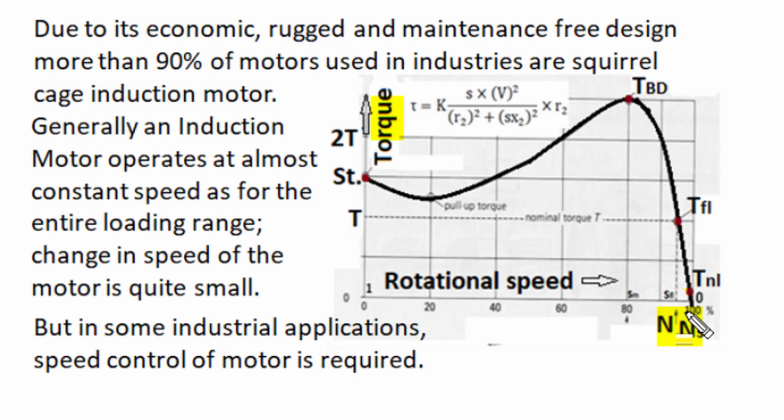At no load conditions, the rotor of induction motor rotates almost at the speed of the rotating magnetic field, the synchronous speed, and the speed difference between the rotating magnetic field and the motor rotor is just 0.5% of synchronous speed, and at full load conditions, this speed difference may become 5% or 6%.